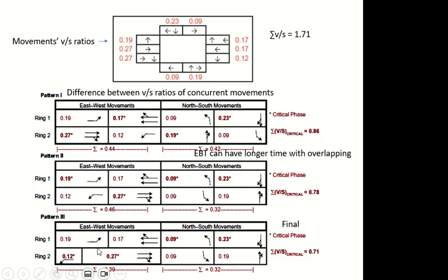Now some of these values are parallel. So I don't need a green time for this one and then another one for this. They are overlapping, they are parallel, right? So I need one green time, not both. Same thing here as well. I don't need a green time for this one and this one separate. No, they are together. So together means what? Green time for this one and this one will be equal.